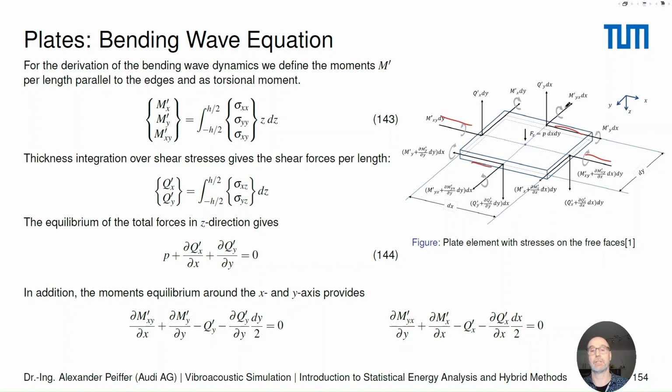And in addition, it's the shear stresses here in that direction, but using the leverage of the plate, because this also creates a moment, because there's always a lever available. And if we do so, we get those two equations that finally relate the Q's and the moment expressions.